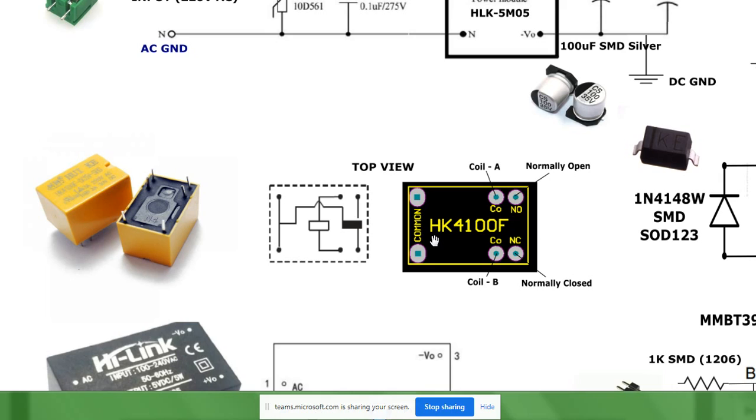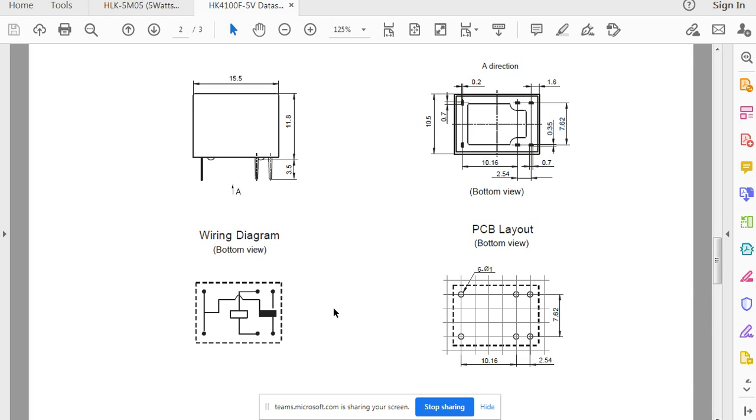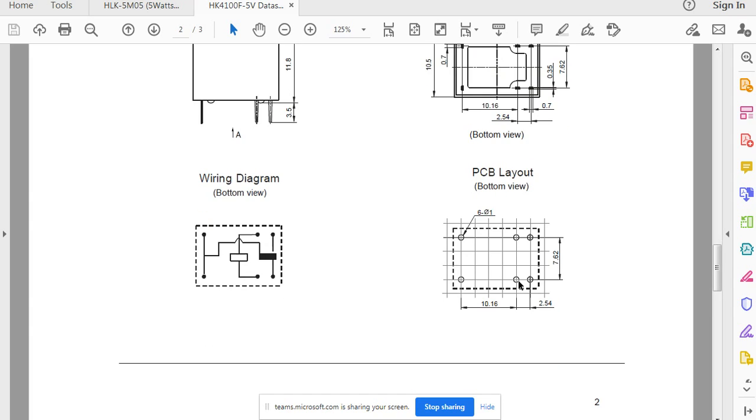So when you actually want to control a device, you have connected a 5-volt signal with the coils. So the device you want to actually turn on, if it was initially off and you want to turn it on by energizing the coil, you are going to connect it at the normally open pin. This is very important, so that you can actually have the control over. So if I go back to the data sheet again over there, now how you are actually going to make the model of this. This is actually the most important thing over there, and I will do that in front of you.